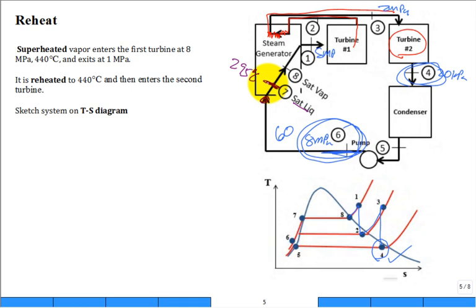Then I'm bringing in a lot of heat at 295, then up to 440. And then over here, it's whatever that temperature was at 2 megapascal coming out of that turbine. It wasn't as high as 295, but it was still close. And so it's good for performance. But this is now something to focus on.